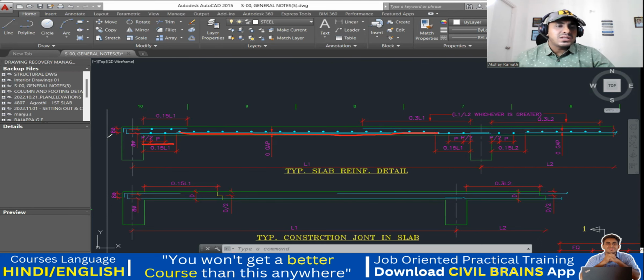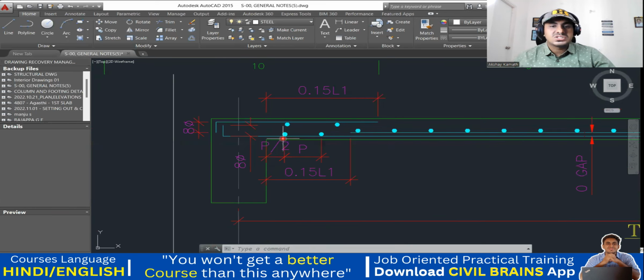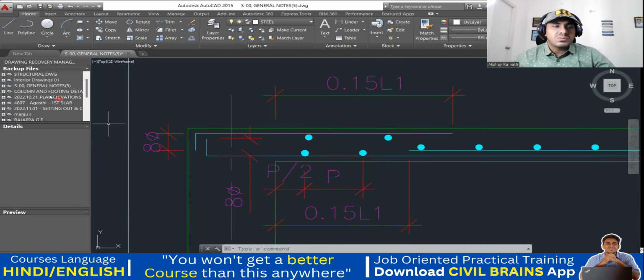Then again, another thing, very important and interesting, which you should understand. See here, this is not a complete development length. If you remember, in the beam we were giving Ld plus 10 times the diameter of the bar. But in the slab, your slab reinforcement will come like this, and only a small portion will get embedded into your beam. That is 8 times the diameter of the bar that is mentioned. Same here also. Got it? So it's not like development length plus 10 times the diameter of the bar.